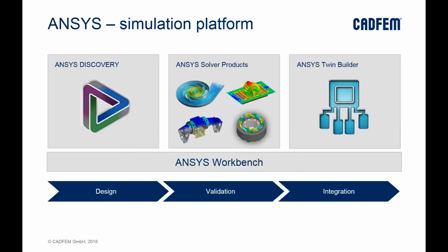Another thing which is important about the ANSYS simulation portfolio is that you have different tools for different parts of the design flow. So you have a part which is called ANSYS Discovery, which is really for the design, for the beginning of the development. Then you have the solver products, which are the most well-known flagship products like ANSYS Mechanical or Fluent, which are for the validation of the product. And then you have this integration of the system, which is called ANSYS Twin Builder. And all these can communicate to each other via an interface, which is called ANSYS Workbench.